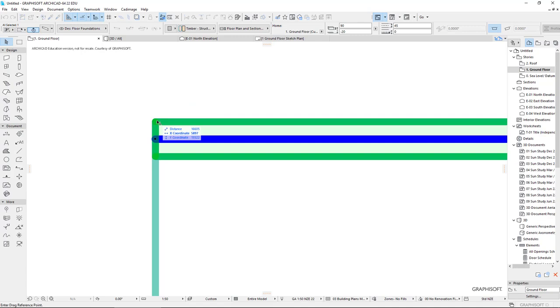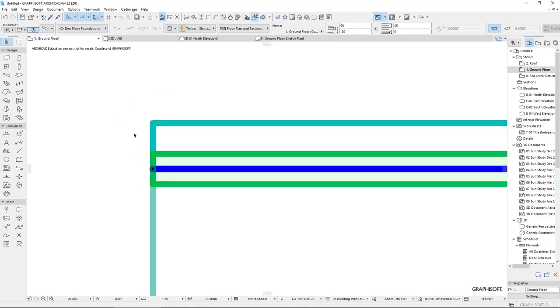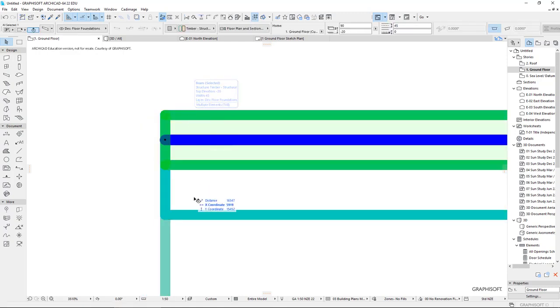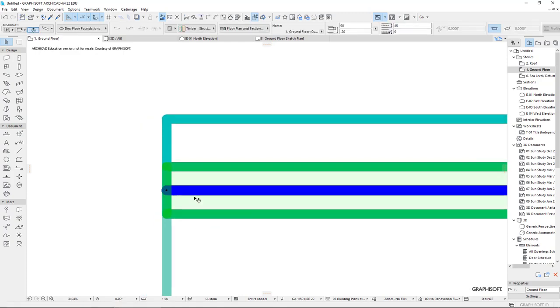Now if you've watched my earlier movies, you'll know there's a technique that I use, which is drag a copy. So we're going to go Control D for drag, click to move, come to this point, and you see the little plus next to my cursor. Let's hit the Control key again, click, and it's got another copy. So there's my first copy, there's my second one.